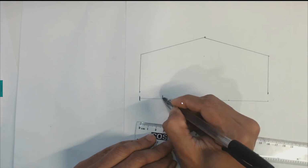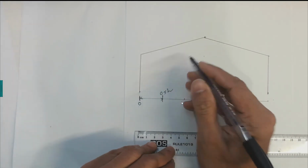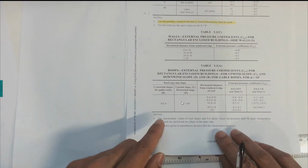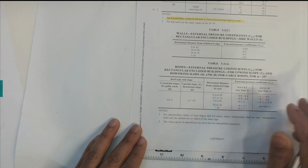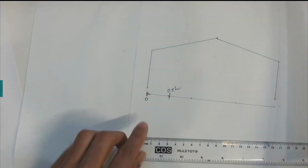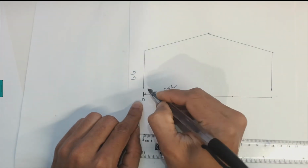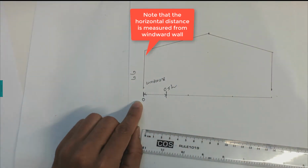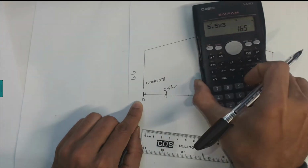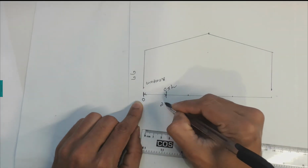Now the first one is between 0 and 0.5h. Why is that? Because the wind is coming, and the standard says this is the horizontal distance from the windward edge of the roof. So we need to start from the windward edge. This is the start of the windward edge, and the wind is blowing from this end, so this becomes the windward wall, and we need to start from the windward wall. That's what is given in the Australian standard. If I substitute h as 5.5, it gives us 2.75 meters here.